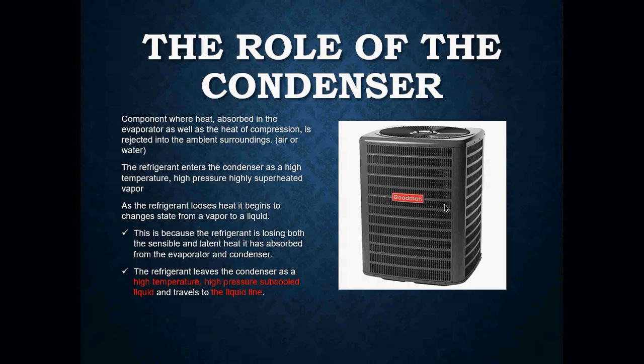Okay? This is because the refrigerant is losing both sensible and latent heat that was absorbed in the evaporator and the compressor. That point in the condenser where this change of state takes place is called the saturation point.